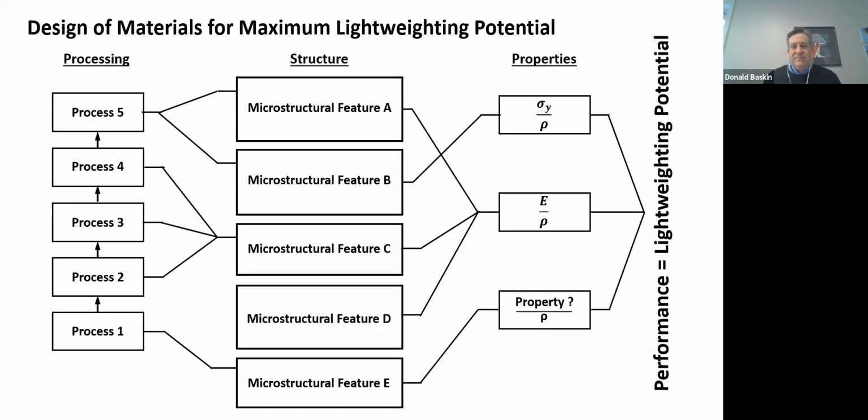Back to this fundamental paradigm of material science: the processing, structure, property, performance relationships, and the fact that the processing, structure, and property all have their subsystems as well. The processing has many different types of processing methods you can do. There are different structures. You want certain structures that give you certain properties. You have to choose the processes that change the material in a certain way to give you these different microstructures, and then those different microstructures give you the different properties you want.